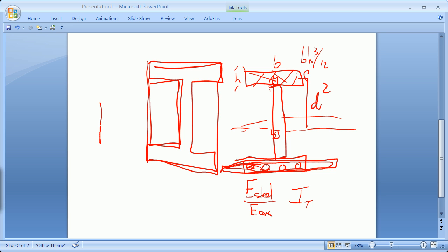That is if you've got a piece of wood, and it's usually not done in reinforced concrete, but if you have a piece of wood and you can glue something a lot stiffer onto that, how do you do the mathematics? Well, you compare the modulus of elasticity of the stiffer material to the less stiff. You expand that stiffer material. That, of course, makes this, instead of acting like just a regular rectangle, it makes it act like kind of a T-beam. It brings down your neutral axis and changes everything. So that's kind of the better.